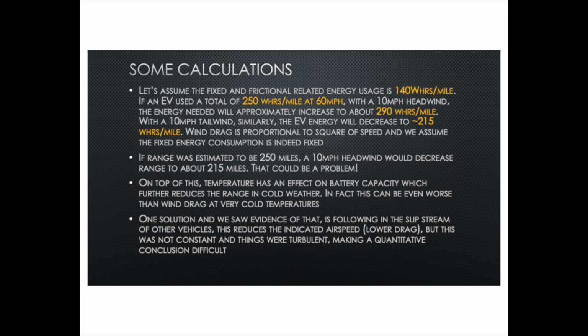On top of this, temperature has an effect on the battery capacity, not so much on the driving itself, although cold temperatures do increase the air density, which may also reduce range. But let's assume it's mostly the battery capacity, and that of course will mean that you cannot charge to the full capacity that you have in warm weather. So that could be an even more significant factor in your range reduction than the headwinds that you're experiencing.